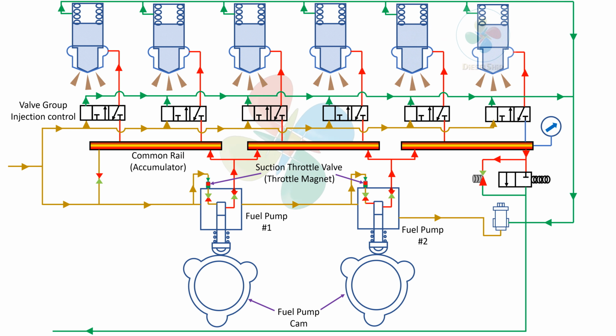Then the valve has to be always closed. So it is a positively closed system. The high pressure from the accumulator, from the common rail, should not enter into the injector unless it is required to do so. That is when the injection commences, right? So that is another function. Another function is that it has to remain closed, as I told you. Another function is to start the injection. When the control module says to commence the injection, it has to commence.